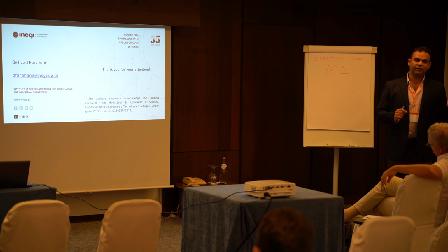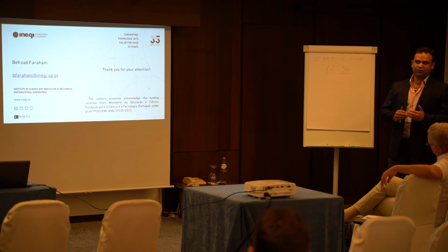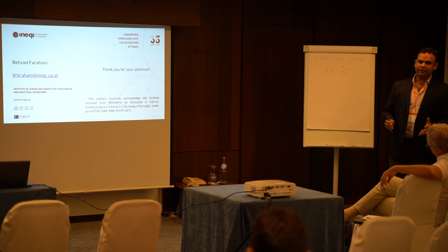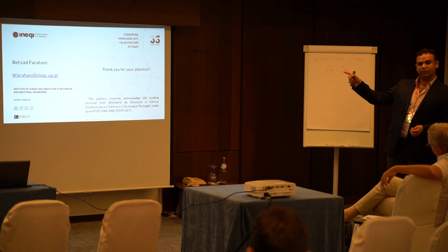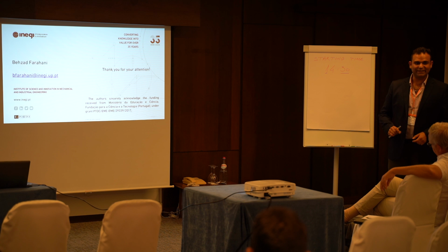Still, we have the same problem as with the long crack. So I'm going to say that if I continue this study, maybe we can conclude that for a certain crack length, longer than this value, although the crack is long and the crack closure should be more visible, it is not going to be true for all specimens with different stress ratios and also materials, because this is aluminum. A better study should be done on the morphology of the voids and the microstructure. This also helps to justify the reason.